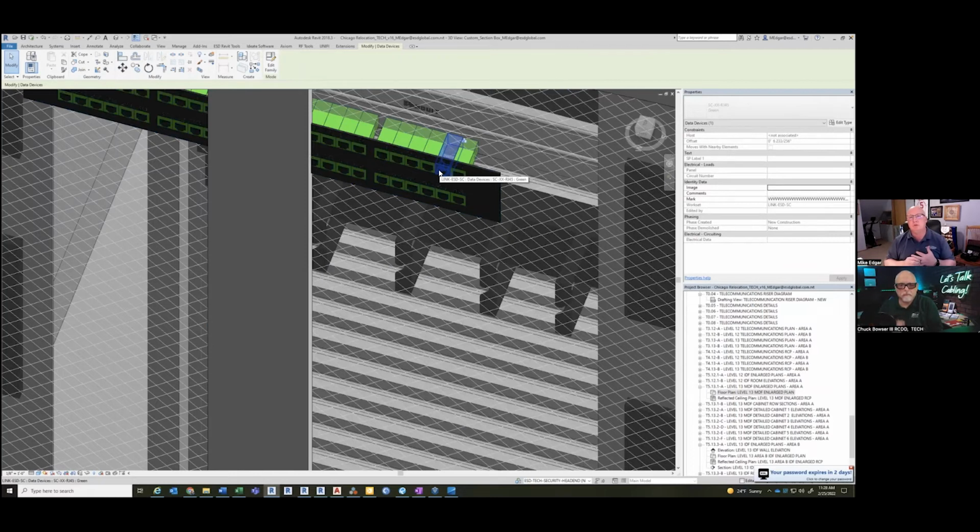So when we're doing the design, we can actually do port assignments. We can run patch panel schedules now. We can do labeling schedules all up front, rather than trying to figure out what the owner needs 10 months from now, when it's in construction and the guys out in the field want information on how the owner wants it labeled. A lot of that stuff can be done here and now.